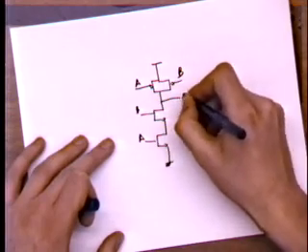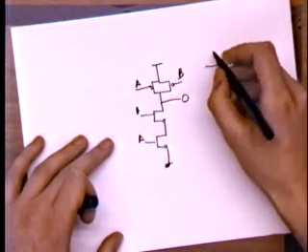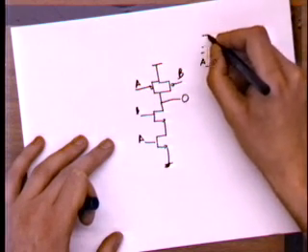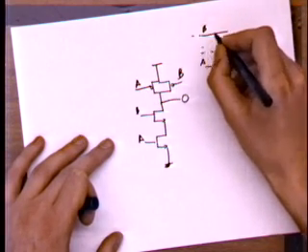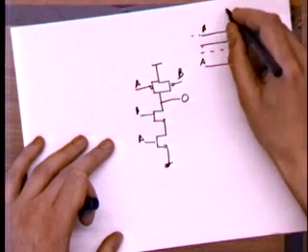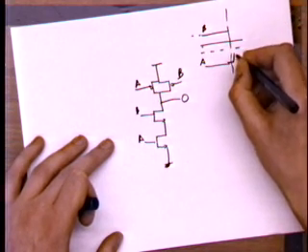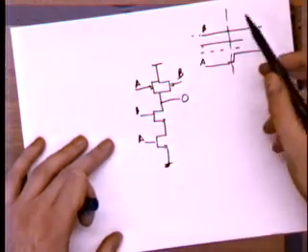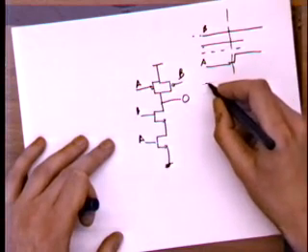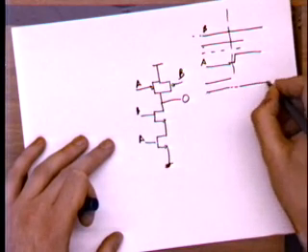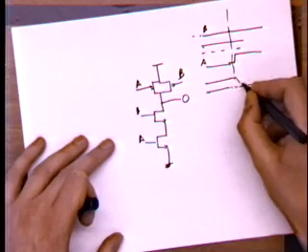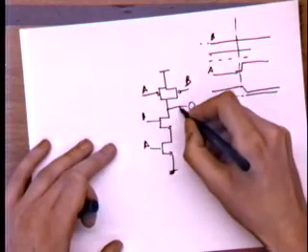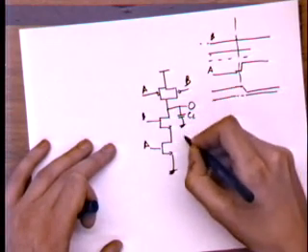This is the output. And we used to be in this condition where A was low and B was at VDD. And what happens at some point is that A goes high and B stays at VDD, right? So what's going to happen to the gate? The output used to be high, and it's going to go low, right? So this is fine. Let's start putting in some CL and some C1, okay?